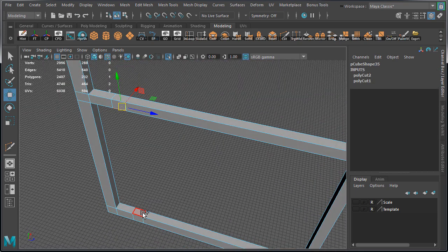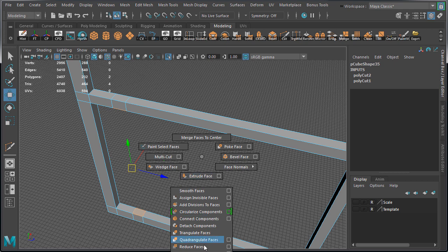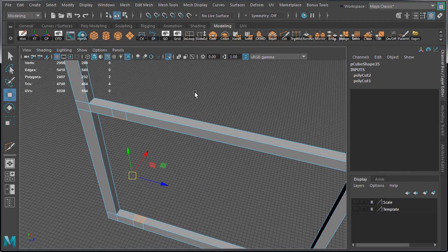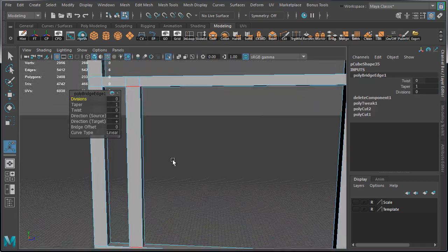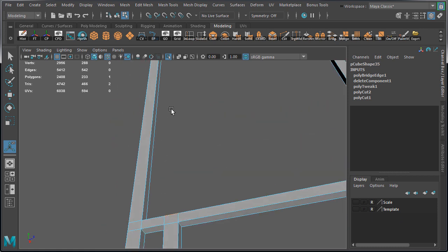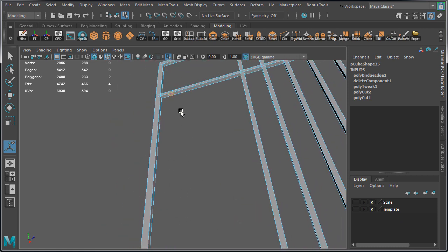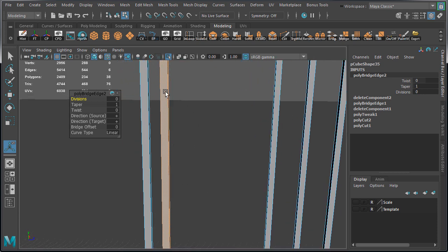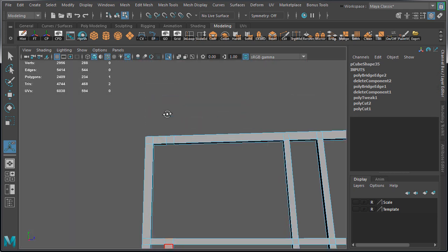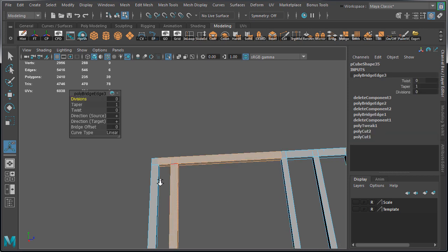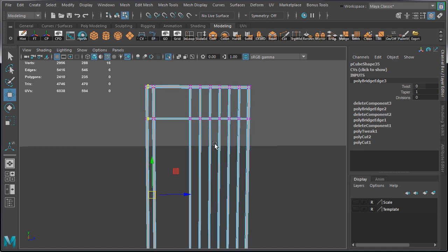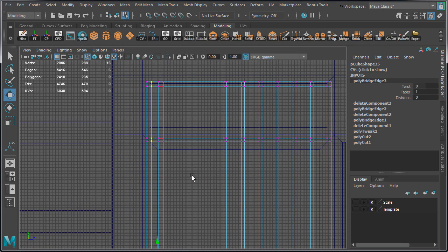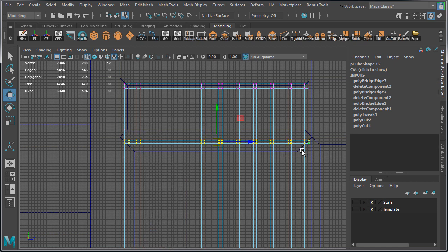Let's select these two faces, hold Shift, right click, hold, and choose Bridge Faces. Then we're going to go up and do the same thing for the one in the middle and the one for the very top. We now created an extra thick bar that is on the left hand side of the door bars. Again, I think creating this might have been overkill. We could have just used an existing set, but sometimes I get carried away creating unique geometry. But I do think it looks better with the extra bar at the very left, kind of giving additional support.